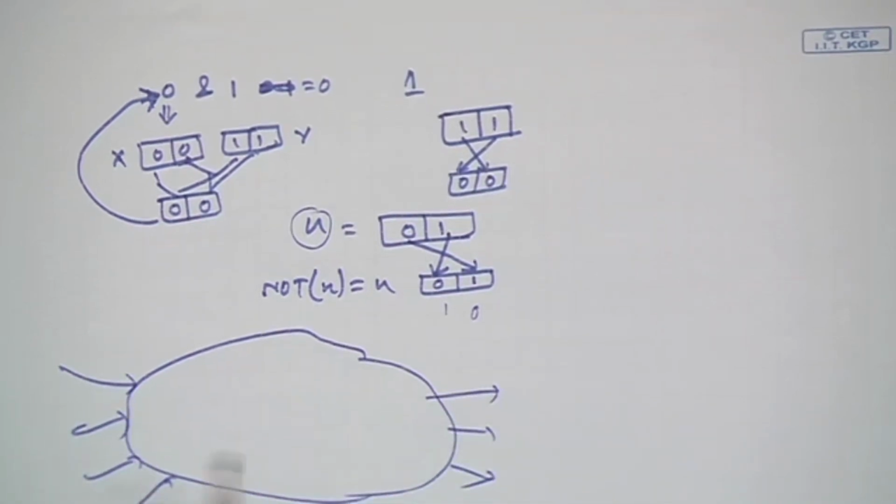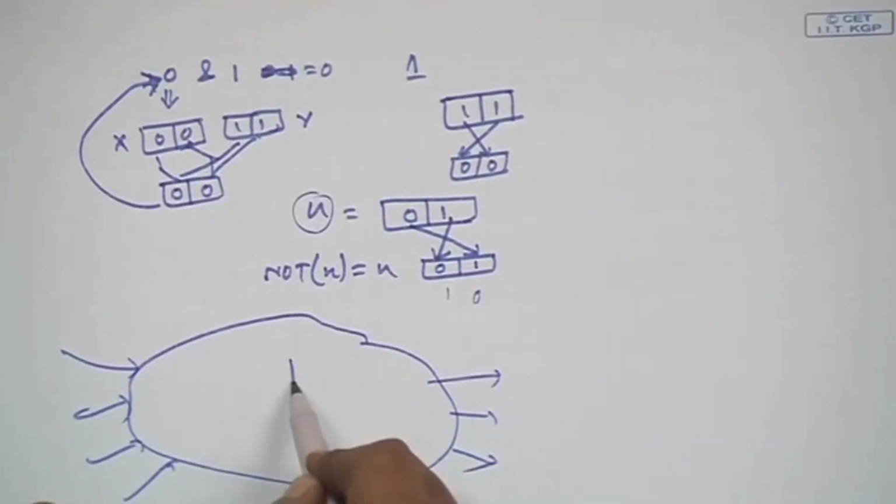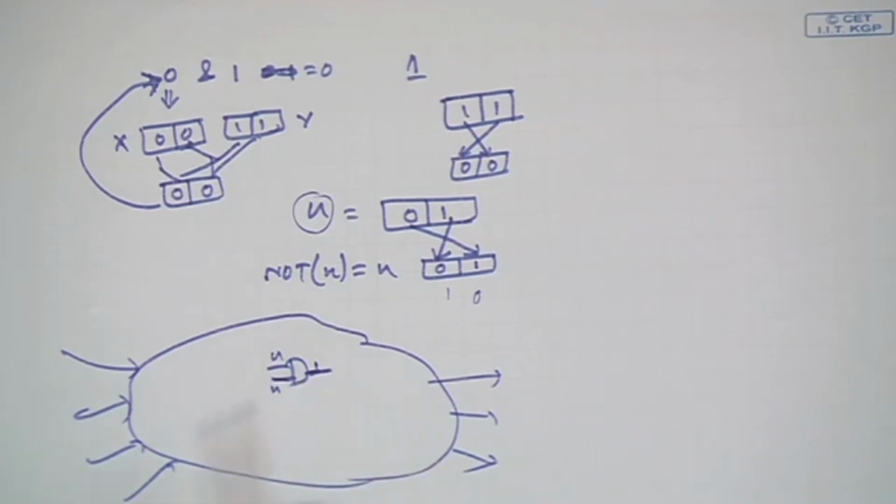Now, if I am trying to simulate this logic circuit, and all of a sudden I want to check what is the output of this AND gate, that is not possible because these values are still unknown. So, if I do a simulation here, I will get a u at this point. Most of the values will remain as u.